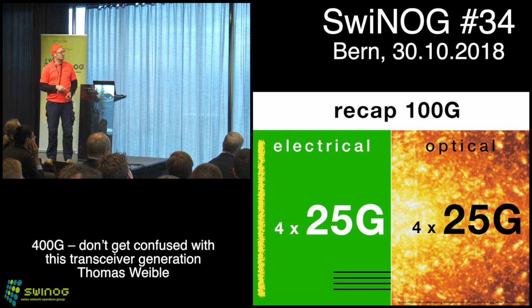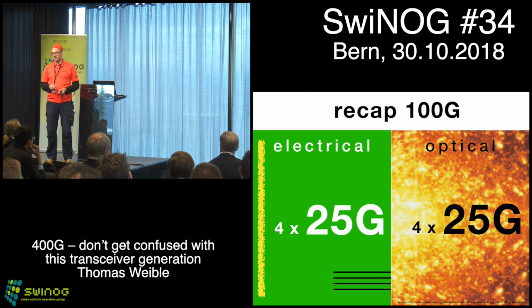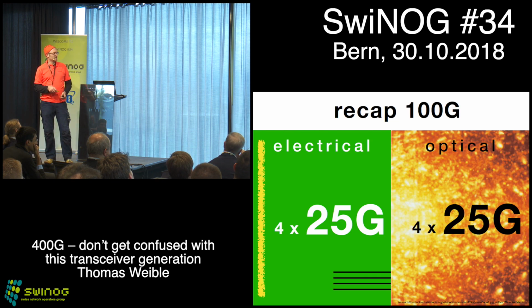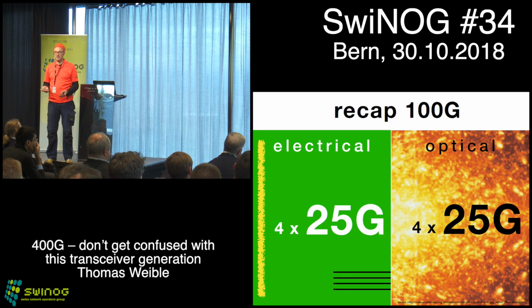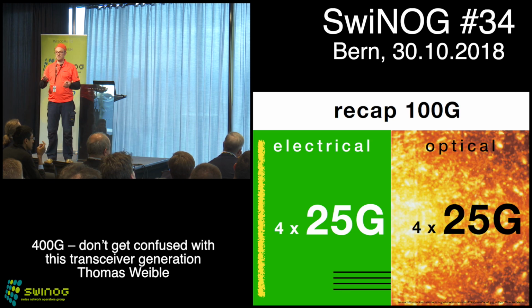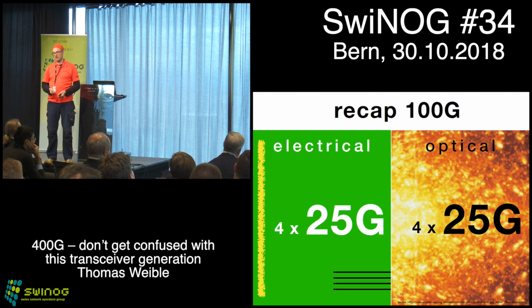And this is driven by 4 lanes, 4 times 25 gigabit. Just remember, it's a single pulse with an on-off keying modulation scheme running at a speed of 25 gigahertz. So these 4 times 25 gigabit give us 100 gigabit. Simple math. Those 4 lanes are connected to an optical engine, which is also driven by 4 lasers running at a speed of 25 gigahertz, and also 4 receivers. So that's what we have already in place for 100 gigabit.